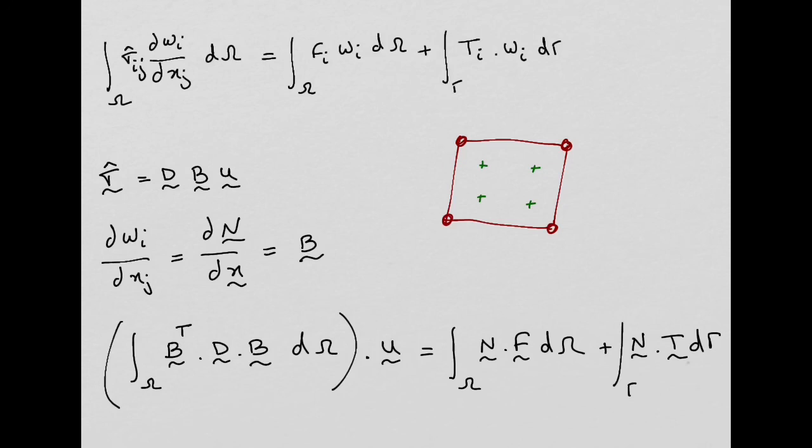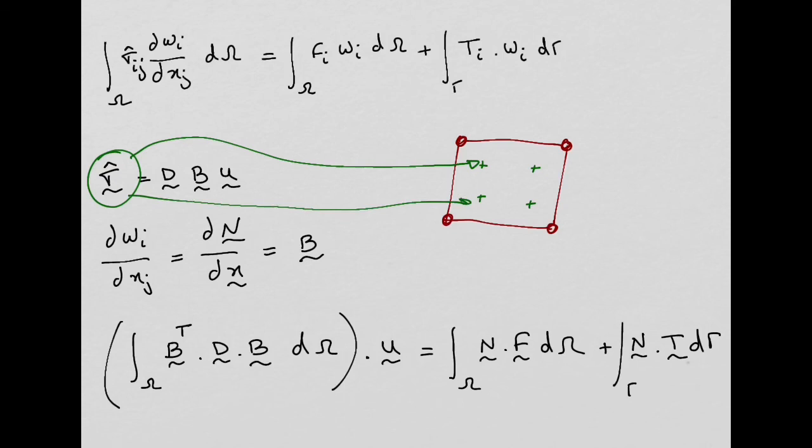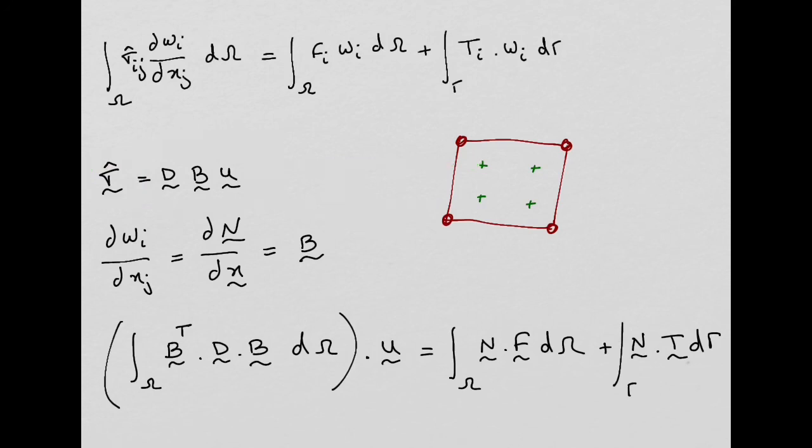And also, everything you calculate, like the strains and the stresses, they are calculated at integration points. Each integration point will have a value of the stress and strain. So you're starting now to get familiar with this finite element terminology.